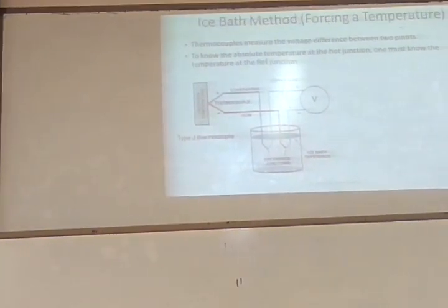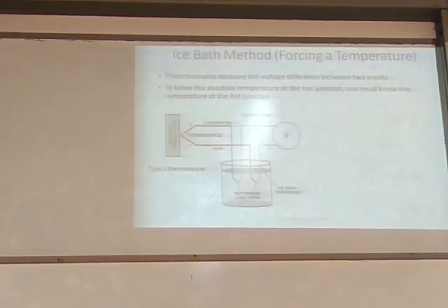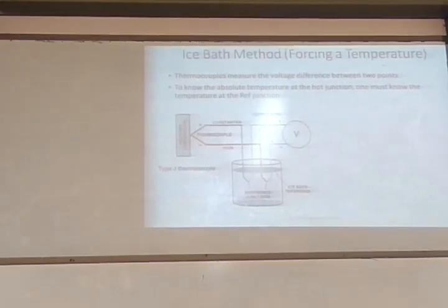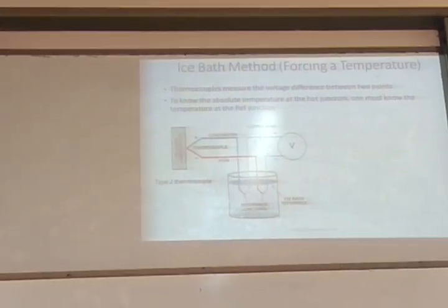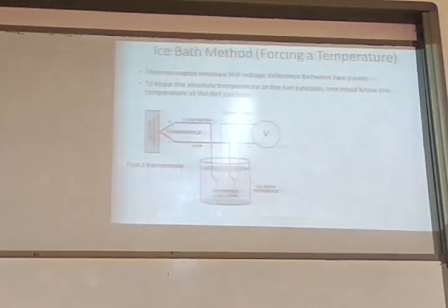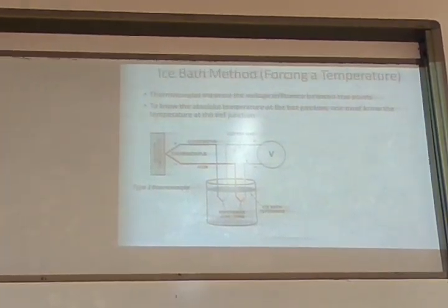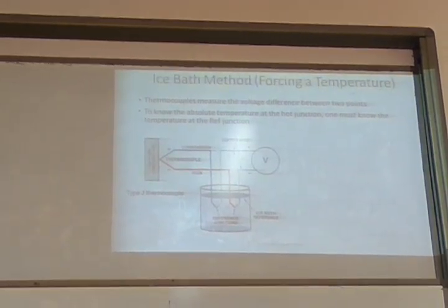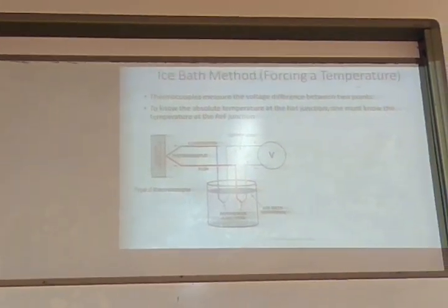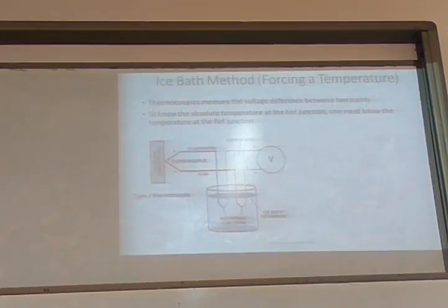The amount of voltage that we get for the temperature difference is very, very little. Let us say for a pair of materials, the cold junction is 0, ice bath only always, and the hot temperature is let's say 150 or 200 degrees Celsius. So the total temperature difference is 200 degrees Celsius. If I use copper and iron, I get 0.1 millivolt, some small voltage proportional to that. Suppose I use iron and constantan, I get 5 millivolts, 6 millivolts. Which one will you prefer? Even if I have to pay a little extra cost, I want more and more signal so that I know whether it is noise or signal.